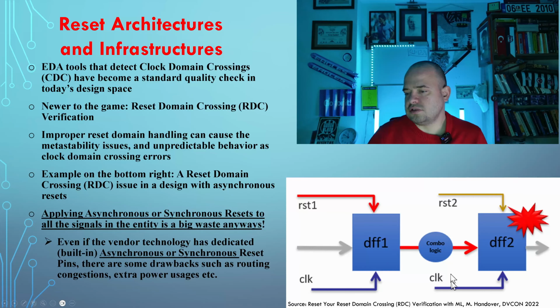Since DFF2 is still actively working, asynchronously resetting the output of DFF1 will result in a setup and hold problem for DFF2. Then the output of this DFF2 would be metastable,